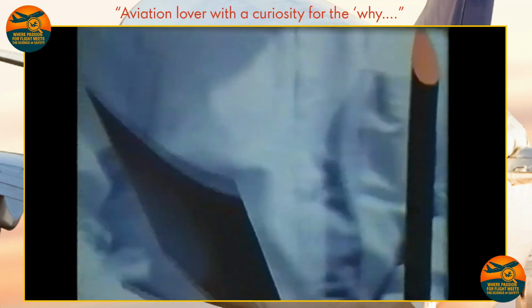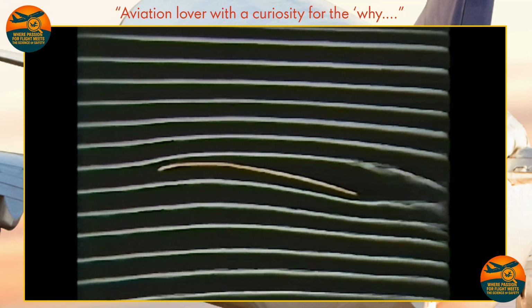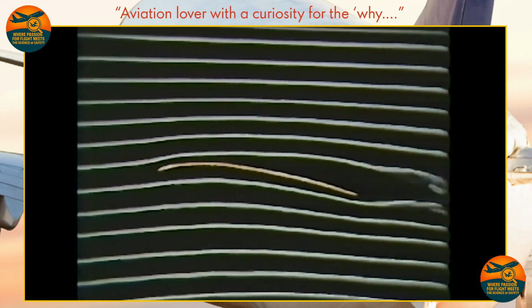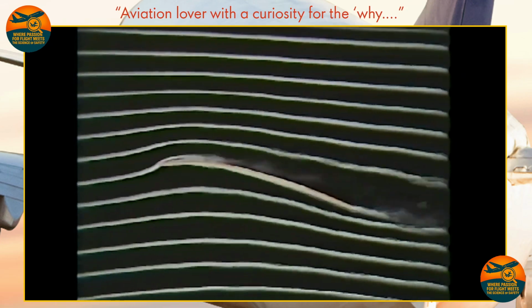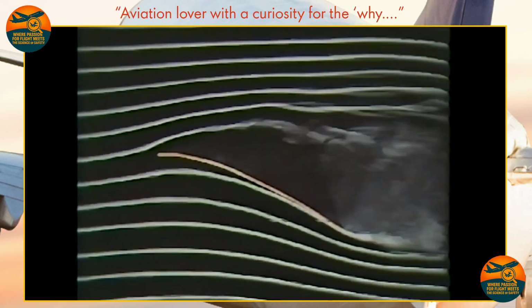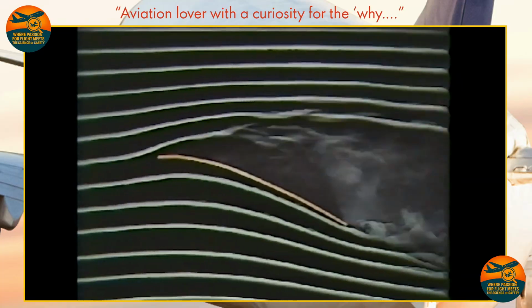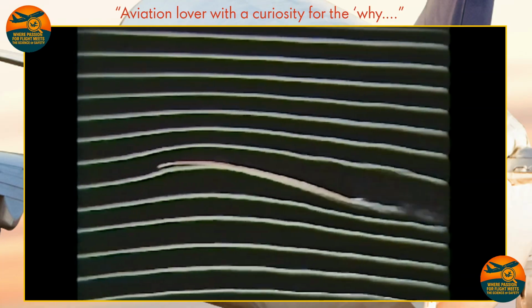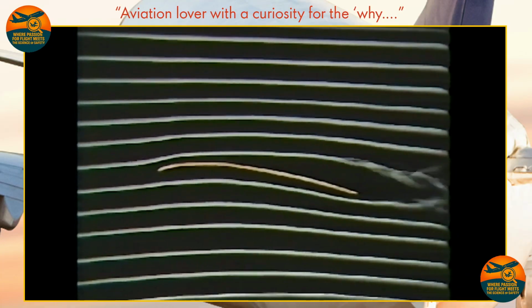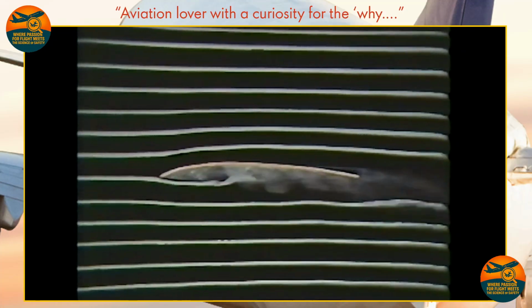Next, a curved plate. This behaves rather better. The airflow is smoother, but it soon breaks away when the plate is rotated through an angle to the airflow. And at a smaller angle, the airflow breaks away underneath where the plate is concave.